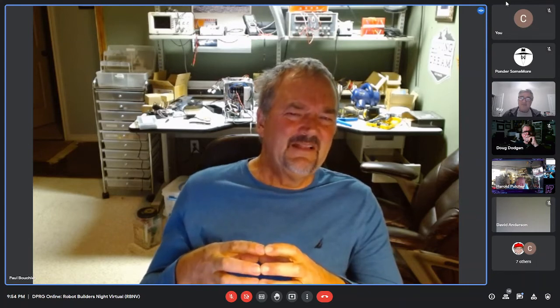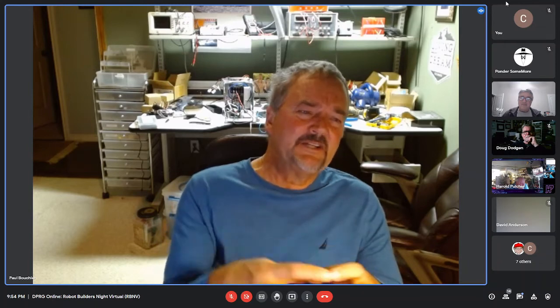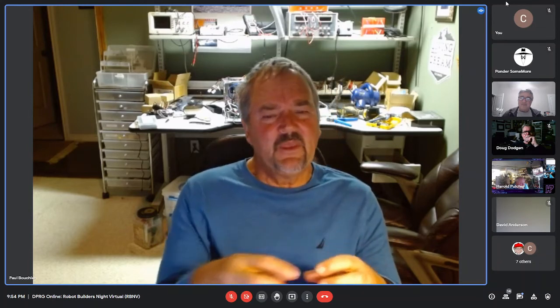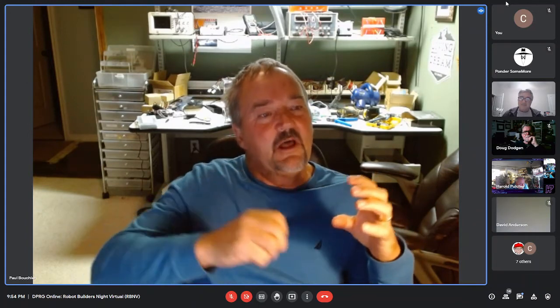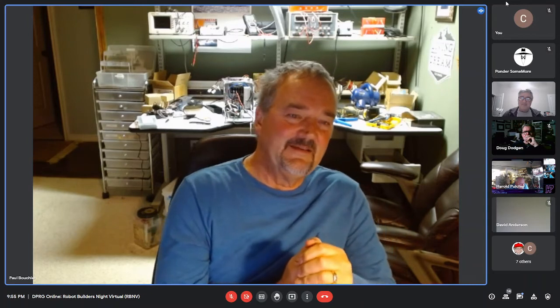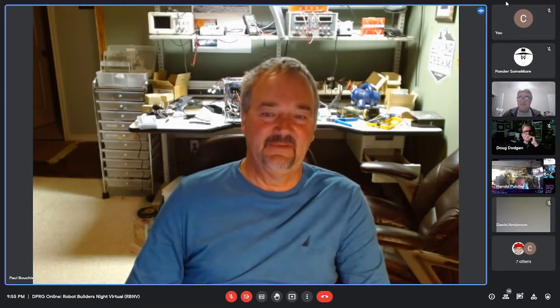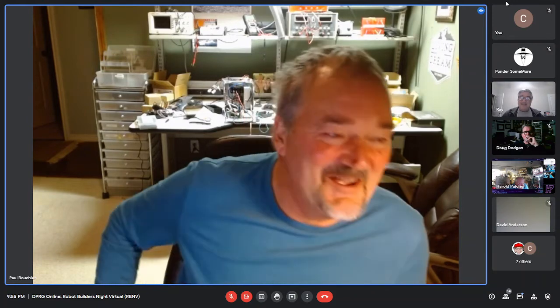There are a bunch of issues with drop-in batteries, and also charging them can be an issue, because if you're charging them off of a car alternator, and then they become full, and then the BMS disconnects the battery, well, all of a sudden your load has been disconnected from your alternator, so you get a big old back spike that blows up the alternator. And so that's why you really need to design a lithium battery as a system. Sorry for going on a rant there, but I've delved very deeply into lithium battery systems before I designed mine.